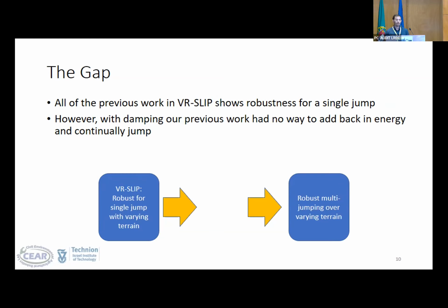So here we see those deviations from the target Y relative. And we can see from this that both the straight leg and the curved leg benefit from torque. They're both compensating, and they're both multi-jumping. However, the curved leg's variable geometry, variable stiffness, variable leg length, adds stability through its ability to compensate for perturbations. All this is done with a single actuator, minimalistic design, open loop control, and single jump optimization process.